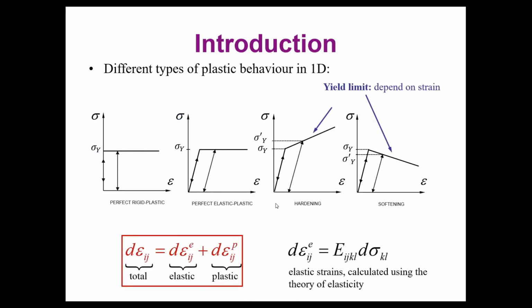So for this bilinear model with hardening, we are going to be able to capture the plastic deformations that are permanent, as well as the elastic deformation that is recoverable. So we are going to have a model that is much more interesting than the linear elastic one, because the linear elastic one is a very limited model that only allows us to reproduce the first part of the real behavior of a material, for example a ductile steel, that is represented by the first line from the origin of these coordinates in this space of stresses and strains.